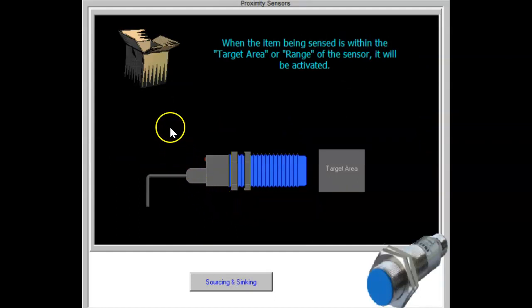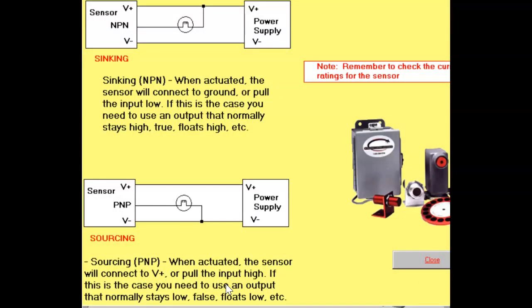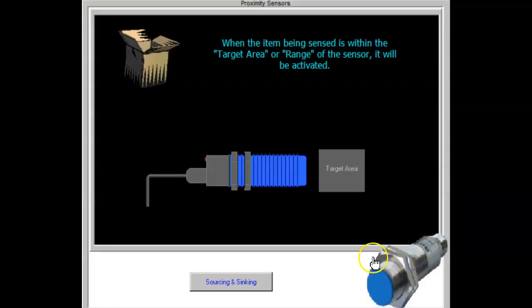Proximity sensors are increasingly becoming popular in a wide range of industrial applications due to their versatility, reliability, and inherent safety. It is possible to use proximity sensors in applications where mechanical limit switches prove inadequate. Proximity sensors can be used to replace limit switches in most applications. They can be used to detect the presence or absence of almost any material without touching the material. Because proximity sensors are solid state, they are extremely reliable, operate at high speeds, and have inherent application and design freedom.